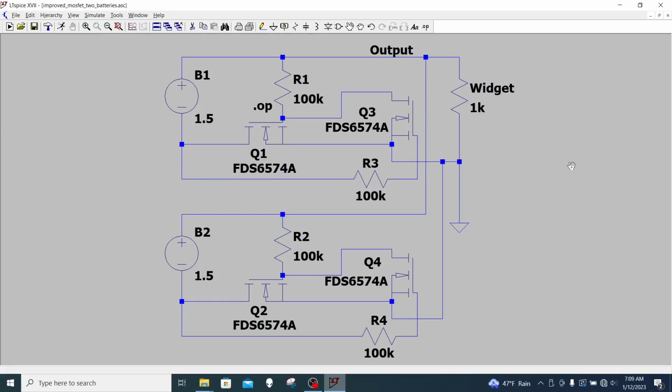I really want to wrap this up now, but I should at least mention that there are improvements you could make to this circuit. You might find an ultra-low power comparator IC that you could use instead of that transistor, and you might essentially reduce the threshold voltage to 0 with that IC substitution.